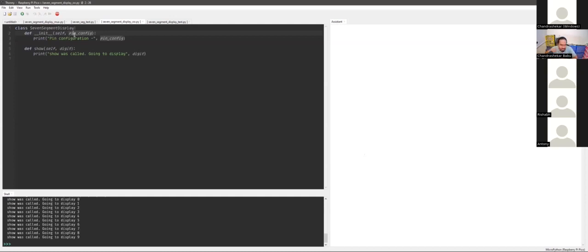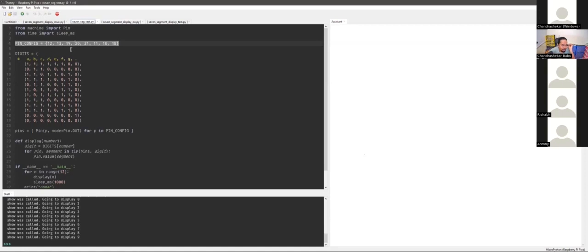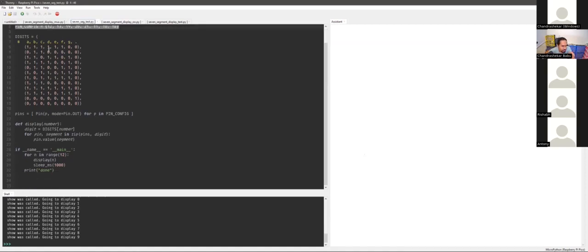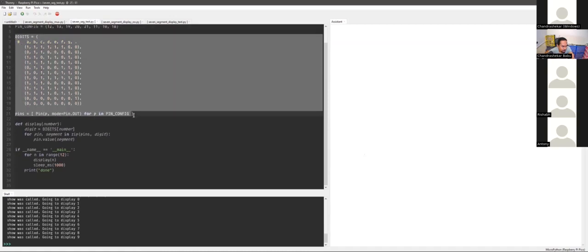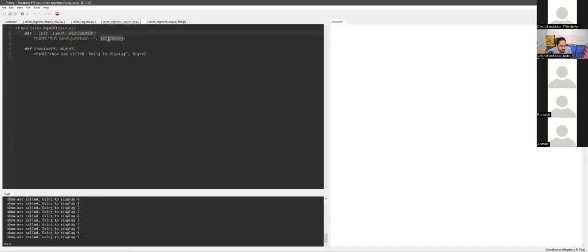Even when you're working with any hardware device, as soon as you're connected to a device through software, we need to program it and initialize it. And we'll do that here. For a 7-segment display, the initialization is very, very basic. We are just going to initialize the pins. Whatever we did here is code. All these parameters, I'm going to take all these parameters. These go in the init method because we're initializing things here. So just copy this. I'm going to paste it inside this class.